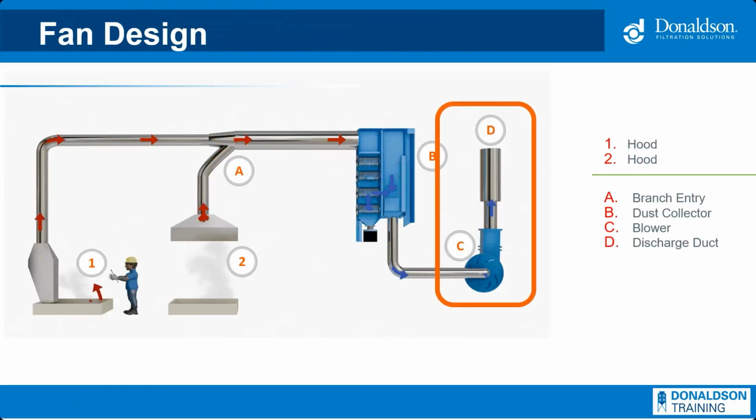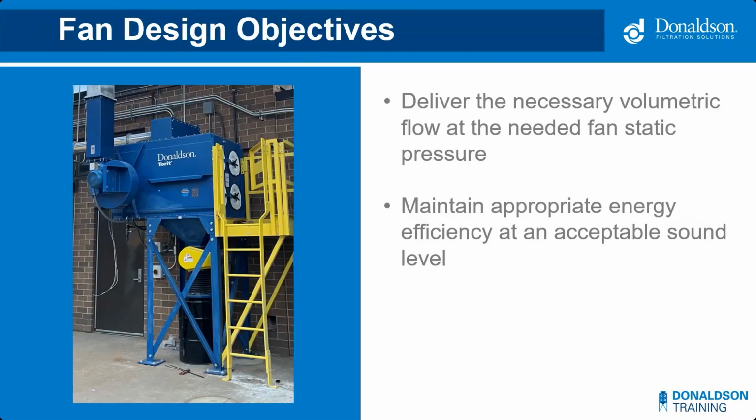When I'm designing a system, the very last thing I do after completing all the airflow calculations is to select and size the fan. The fan is an important component of the ventilation system as it supplies both the energy to move the air through the system, or the velocity pressure, and the energy to overcome resistance to flow, or the static pressure. It has two job responsibilities.